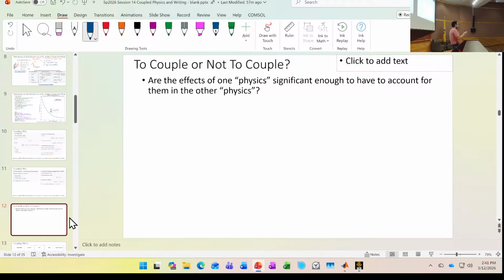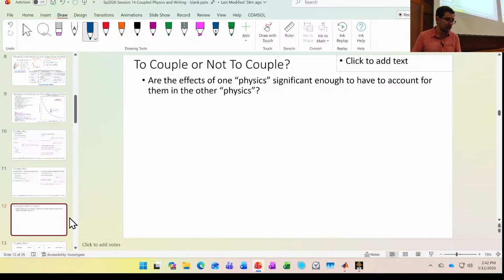If you cannot, for example, we're doing an example with flow over a heated rod. By using fundamental principles for the viscosity, the density, and the heat capacity of the fluid, you can try to approximate, since you don't have a heat transfer coefficient for that particular system. You can try to run the simulation. But often, you're going to want to avoid having to simulate more than is necessary.